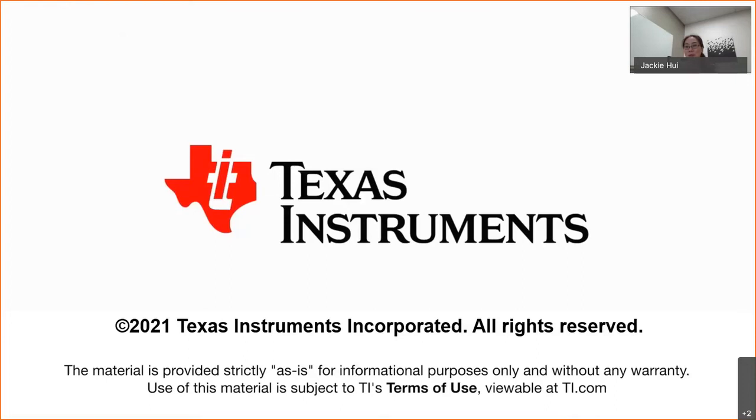Things to pay attention to is some of the GaN FETs have pretty stringent requirements on what your gate voltage should be. For example, typical is 5 volt, and for some of them, if you go beyond, say, 6 volt, or hit about 6 volt, you risk damaging the device.